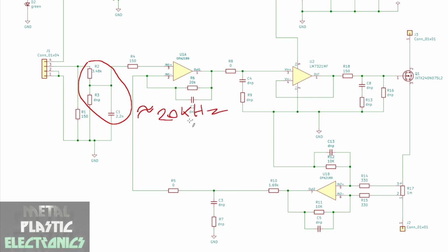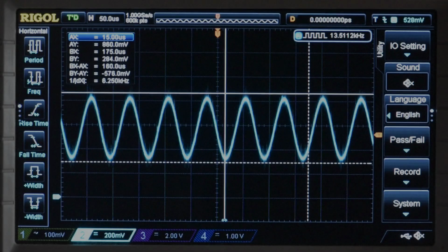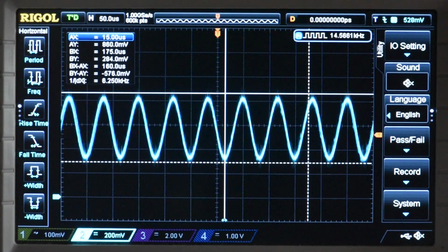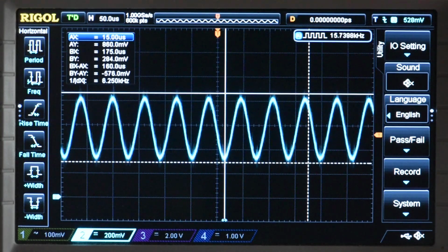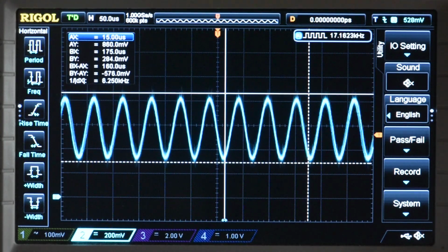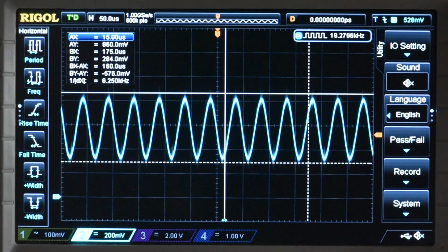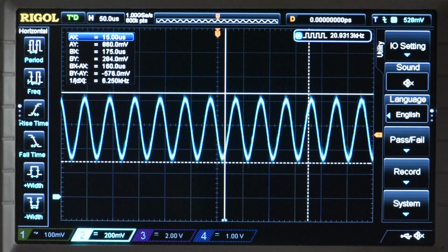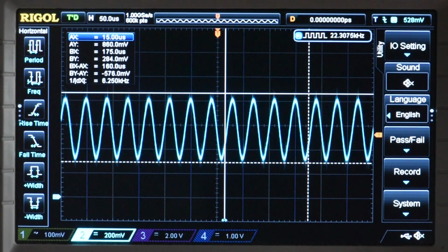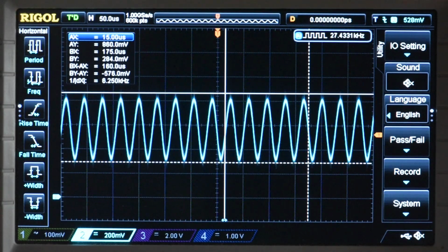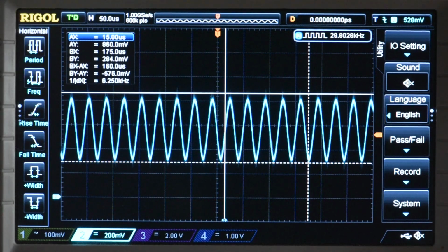Of course, that won't help with high-frequency noise in the drive loop, but it should help with noise going into the module. With the filter in place, the gain is now pretty flat through 16 kHz, then starts to drop ever so slightly, maybe down about 3% as I get into the low 20 kHz region. Just a nice smooth gradual drop as the frequency goes up.